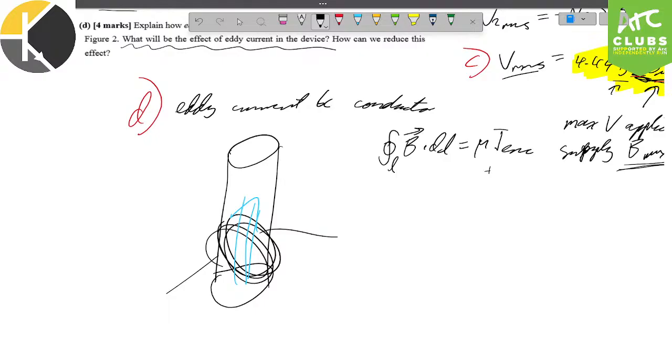There's probably some J term when you put it into the time-varying form, but just understanding this, the flux generates currents, okay? And that's all that eddy currents are. So if I have another coil in here, that's going to generate some manner of current. But if my core is conductive, I'm going to generate those currents inside the core, okay?